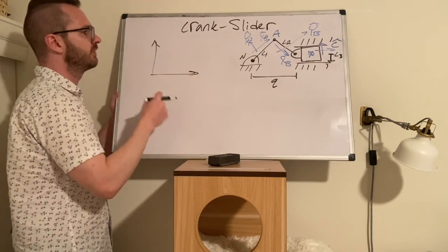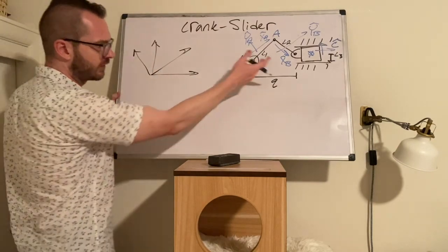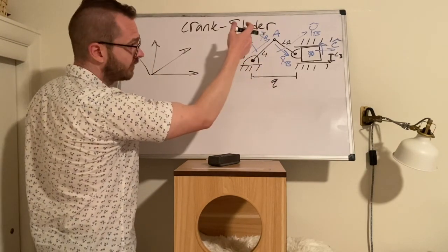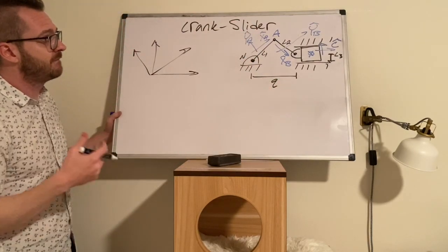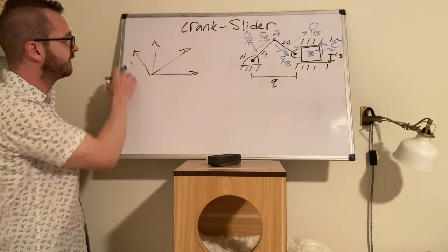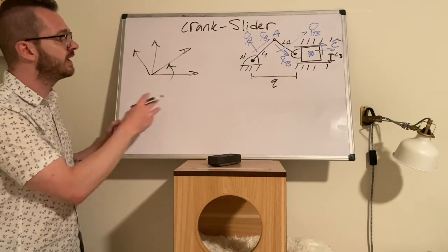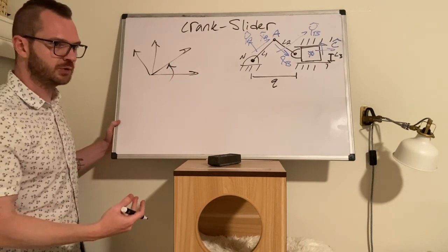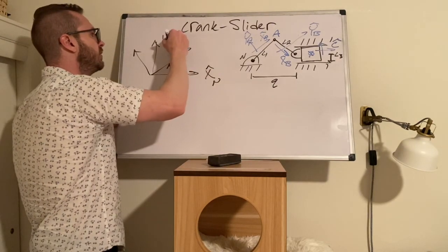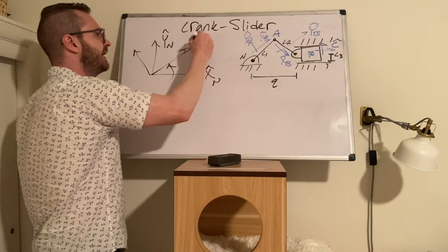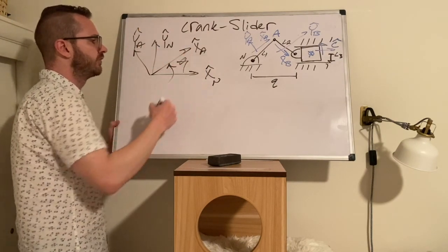So what are we gonna do? We're gonna do our diagrams. We're always going to draw it in quadrant 1. It doesn't matter. For example, XB is currently in quadrant 4, right? It's pointing down and right, but the trig expressions work. If you just derive it from this initial quadrant 1 diagram with the sines and cosines, even when it's in quadrant 4, it's still true. XN, YN, XA, YA. And here's our first rotation, theta 1.